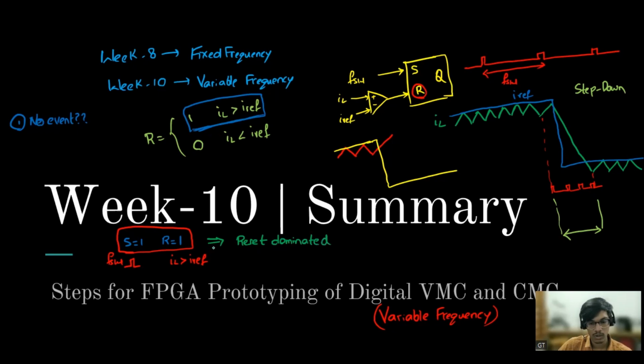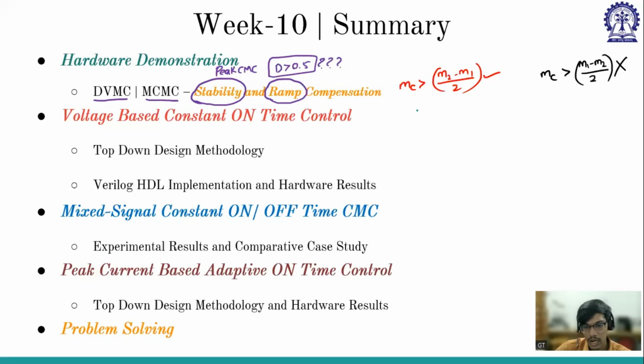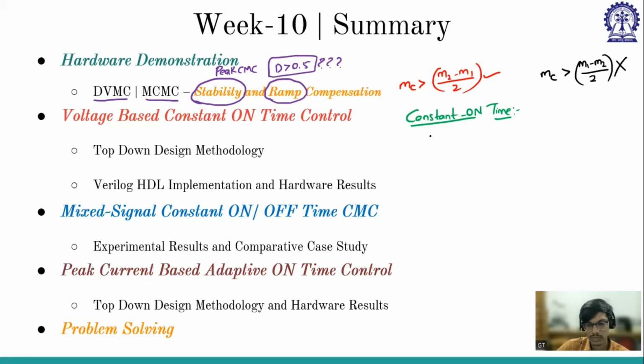These are clear. Okay. Now, coming to the other case where we are talking about the constant on time or off time. Say, let us talk about constant on time, which is a peak or valley? Valley, yes. So constant on time, off time, on time, off time. Shankar also mentioned valley. Yes, it is valley current mode control. So it is again valley.